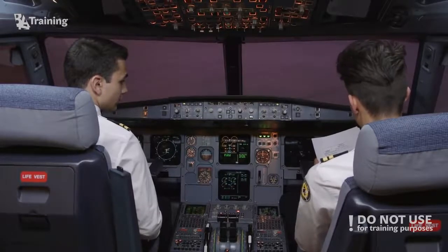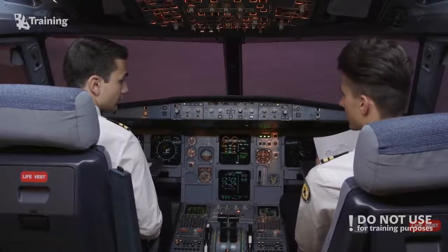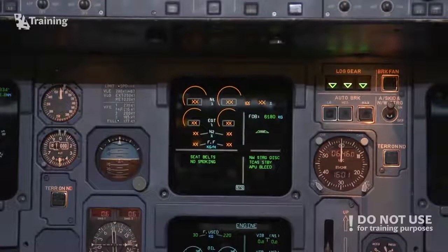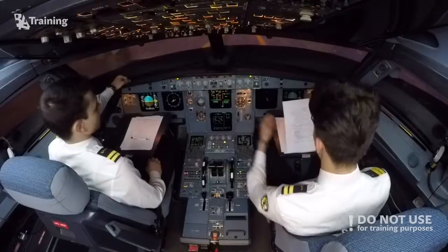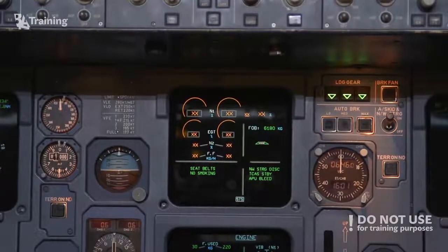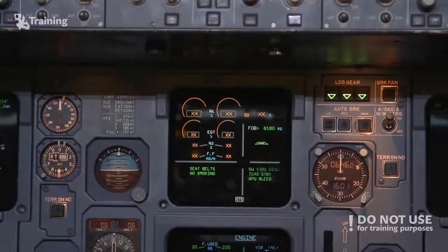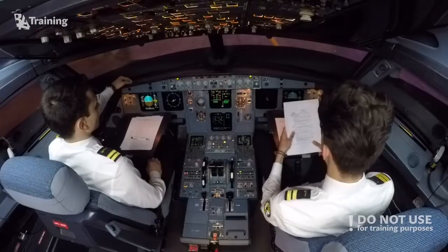Note, if both engines are started manually, the following procedure applies to one engine at a time. When all engine parameters are available on the upper ECAM display, which means no amber cross is displayed on the upper ECAM, which is not the case right now. Engine manual start, push button switch on, start valve check in line, oil pressure increase check, N2 increase check.